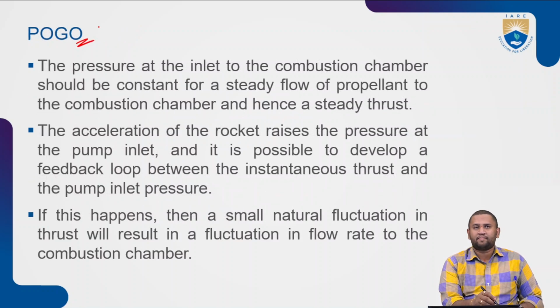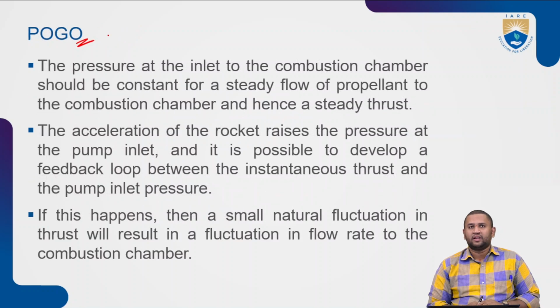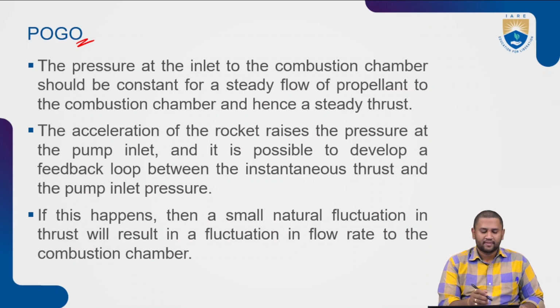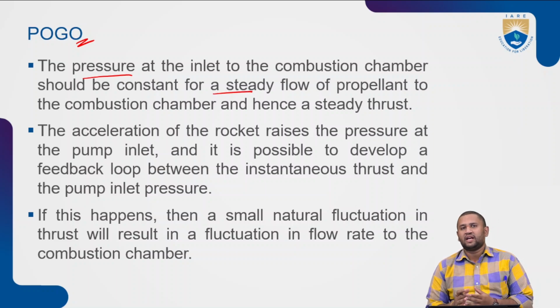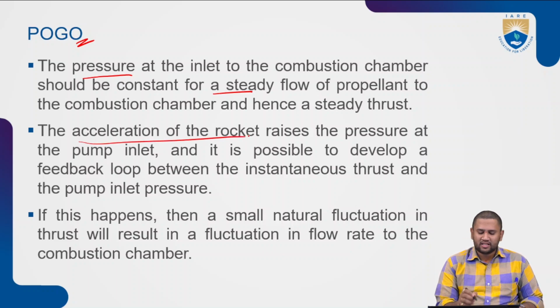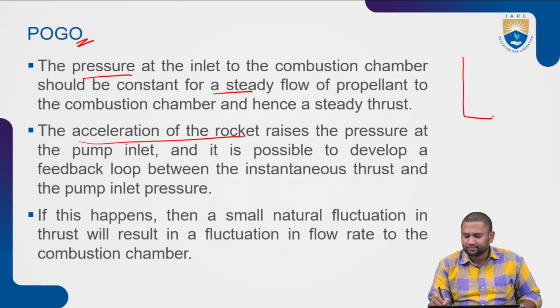A second concept is pogo. Naming-wise it might seem unreasonable, but we'll try to understand the concept. The pressure at the inlet of a combustion chamber should be constant for a steady flow of propellant towards the combustion chamber, hence giving a steady thrust. But the acceleration of the rocket raises the pressure at the pump inlet, right?